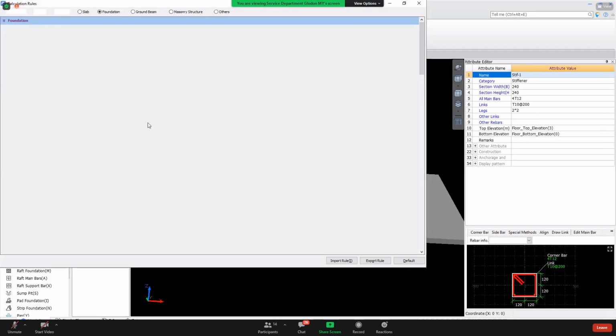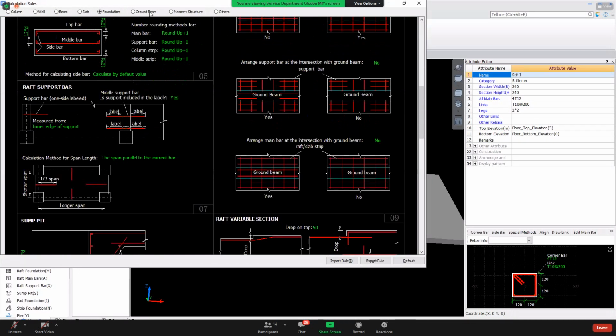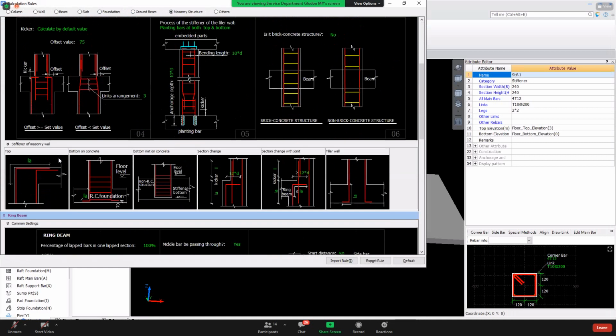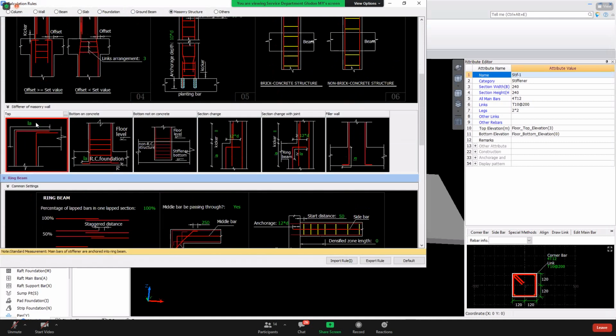So the default settings over here, you can see anchoring to the top part, LA. Instead of LA, let me make it easier. Let's just change this LA to 1000, right? Easier to see. And then after that, bottom concrete, this one I also changed to 1000, so that it's easier for us, right?